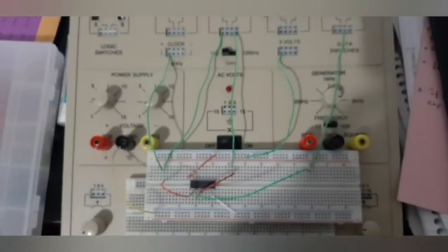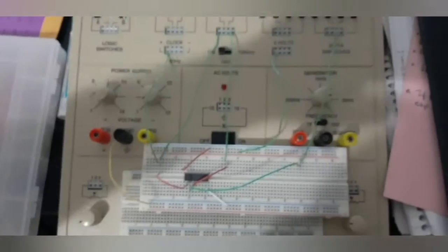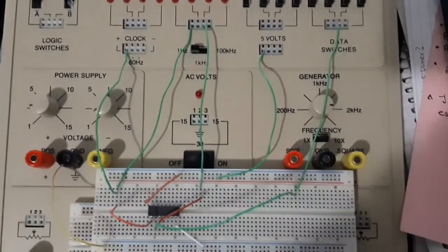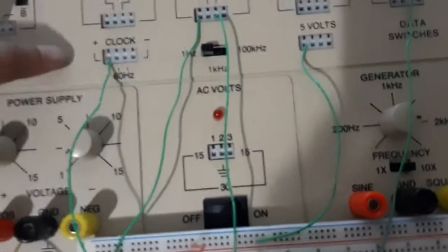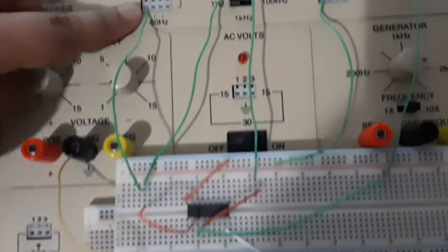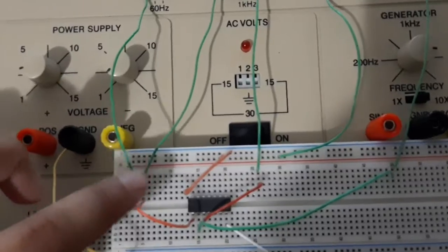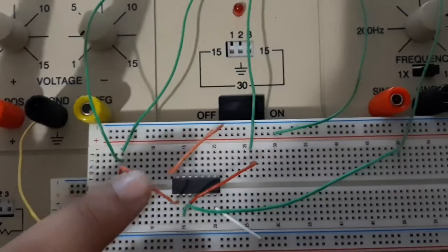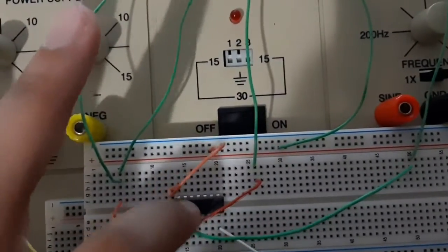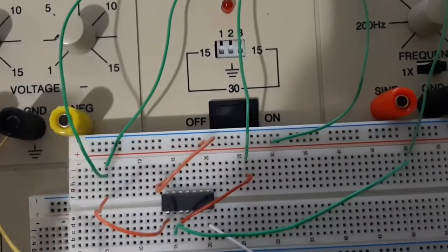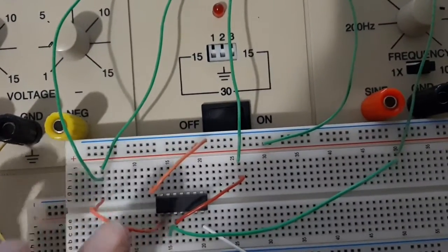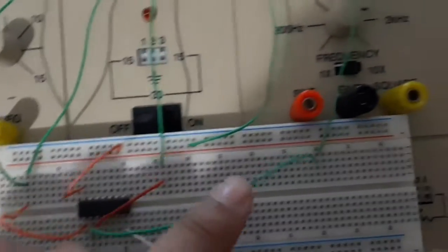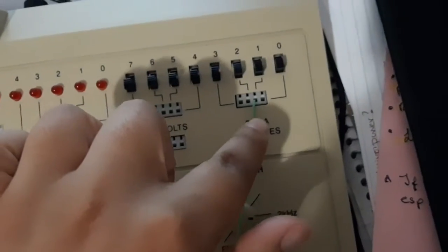Let me move my hand. I'm going to explain a little bit more about how it's connected. And now to see how this circuit is connected, we have the 1 Hz clock square wave signal connected to this row. I'm going to focus in a little bit. To this row, which has a wire connecting it to this IC chip 7432, which is the OR gate. So pin 1 is input A, and it's connected to the square wave. Pin 2 is input B, and that is connected to switch number 1.